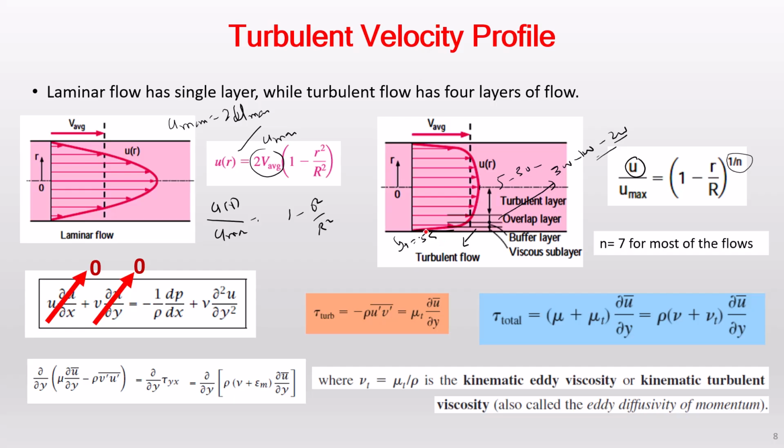The maximum shear stress is in the wall region, where we will have the maximum pressure loss as well. So if you want to predict very accurate values for the pressure drop, the coefficient of friction or the Darcy friction factor, then you should resolve your viscous sublayer. So for that we will keep y plus 1. And I will give you one more example where I will keep y plus around 10. I will compare what will happen if the first cell height is not in the viscous sublayer but in the buffer layer. And maybe you can try one more case yourself where you keep y plus greater than or equal to 30.